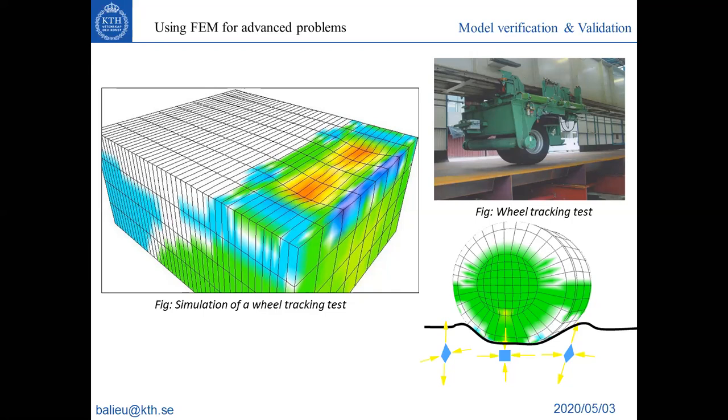If you have a road which has a different geometry, which is wider, or which has different boundary conditions, so it can be confining. There are different possibilities of performing this test. So this is totally depending on geometry. So you cannot deduce intrinsic material parameters for this. So this is only used for validation.